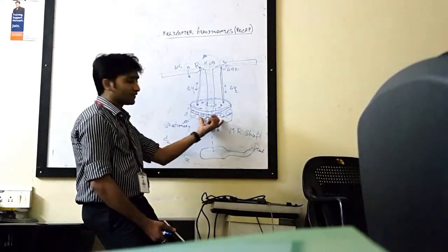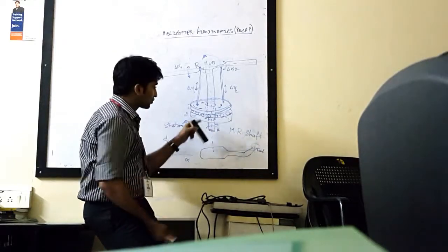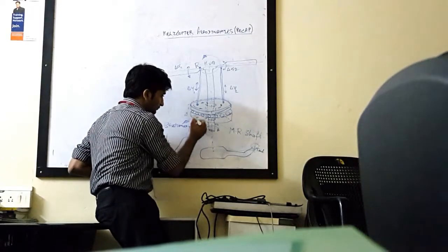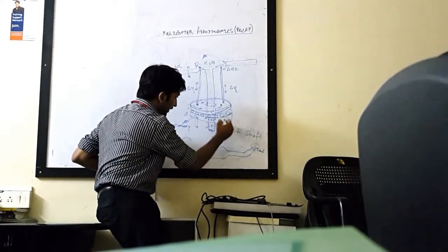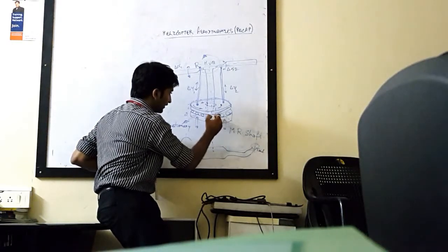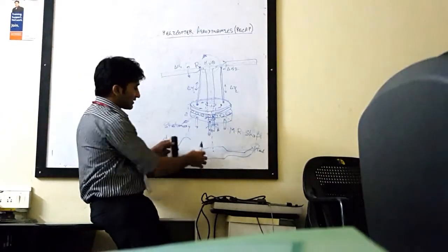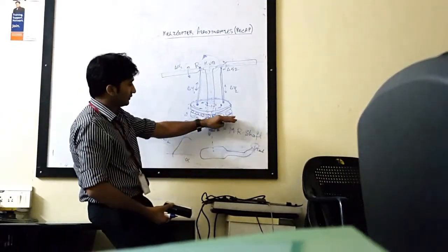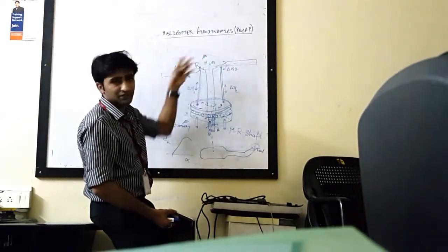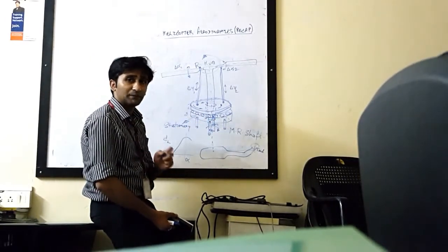Right? So now this bottom plate is held stationary, and there is some assembly here through which you can change the motion of this swash plate. What assembly is that is, you have a rod here, you have another rod here, you have another rod at the front, you also have another rod at the back. Okay. So now if all the rods are pushed up by some mechanism from the bottom side, the bottom plate will move up, the top plate will move up, both the control rods will move up, the pitch gets changed simultaneously in terms of vertical climb only, and vertical climb and vertical descent.